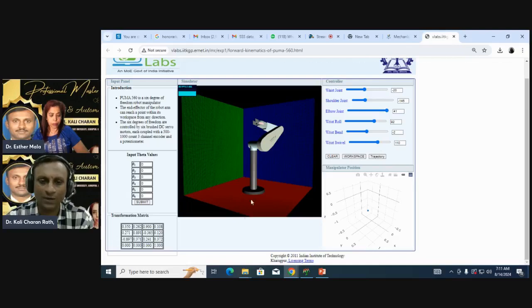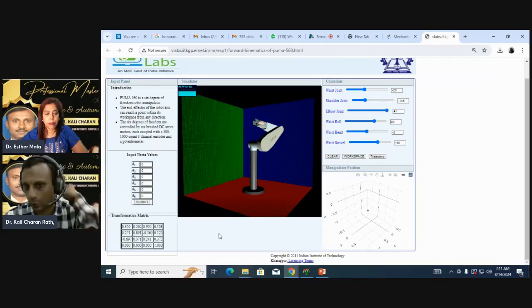Now, if you see the workspace here at this particular position, what is the transformation value? This is the transformation matrix, which consists of the rotational transformation matrix and the position value, scale factor, and perspective matrix. Okay. Now at this position, the position is 0.108, 0.120, 0.372.